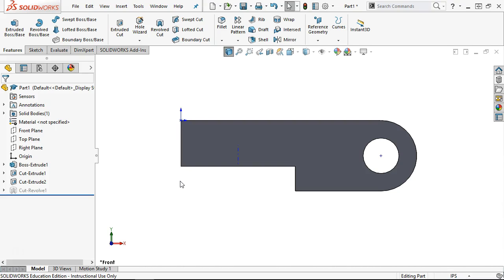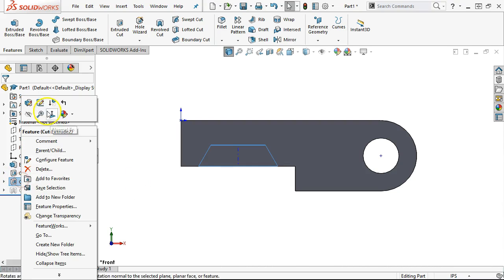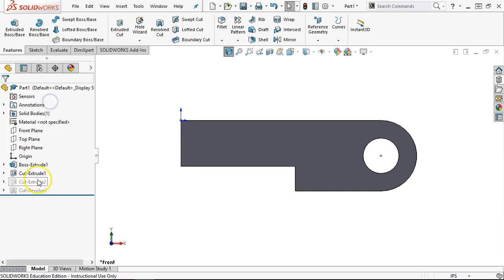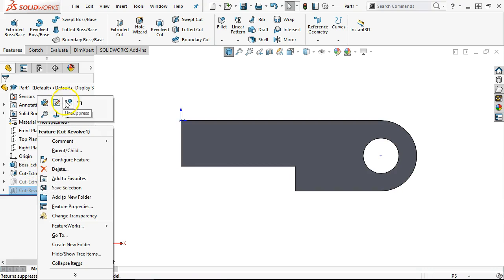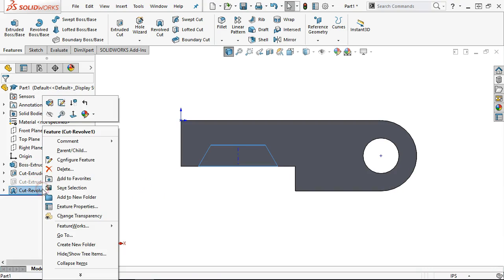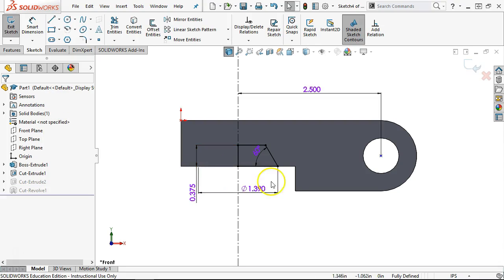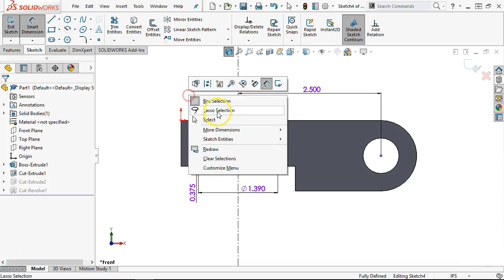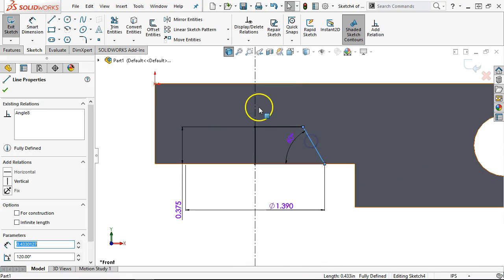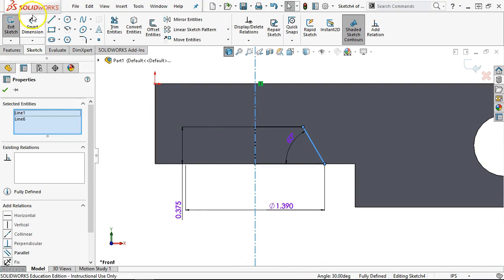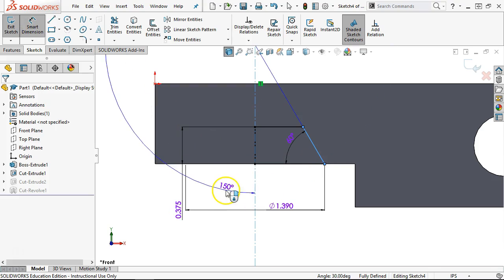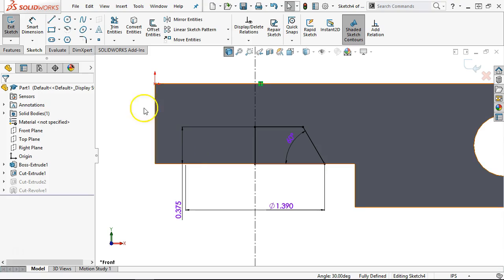All right, so the other question is then, since we're given 60 degrees on the included, and no, did I do that right? So I'm going to switch back, and this would be a good place for the configuration so that I can do my what-if scenario without switching back and forth. So let's just mirror that one over, because I don't think that the smart dimension kicks it over to the other side.